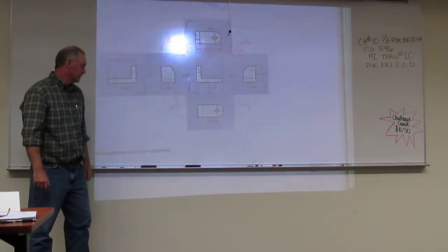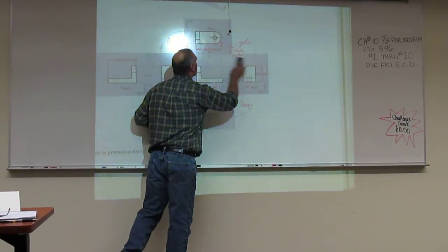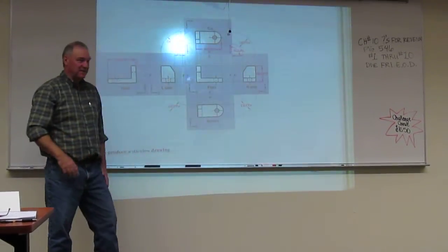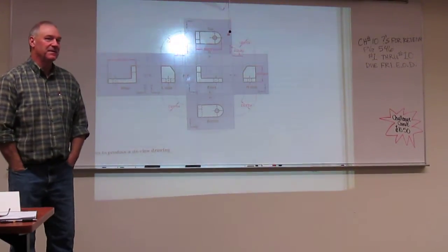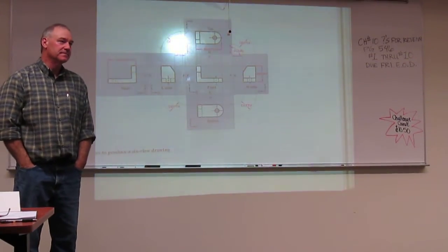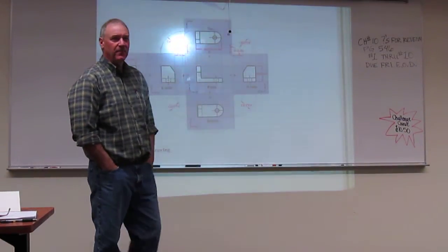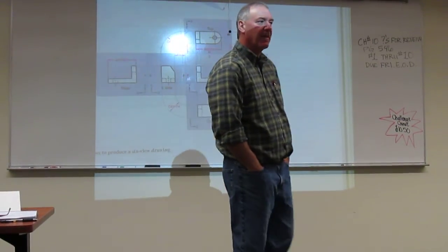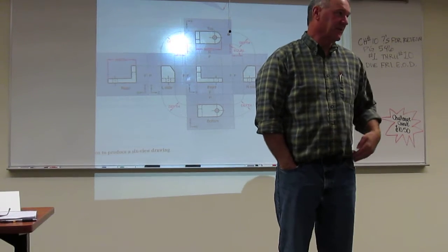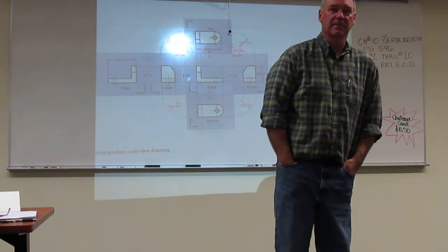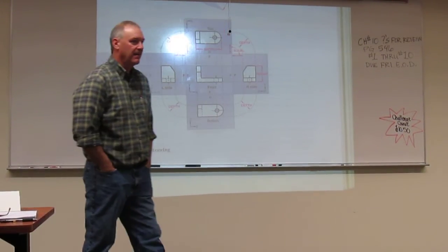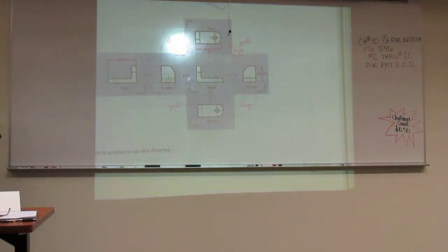Do people who are looking at drawings feel more comfortable with the front, top, and right? Yes, they do. That's what they're used to. And keep in mind, the person building this stuff looks at it maybe half an hour a day, and the rest of the time, they're actually constructing the object. So you almost have an exception to the rule, if you wanted to show the right and you needed the rear, to throw the left in, even though it didn't show additional information. Yes.